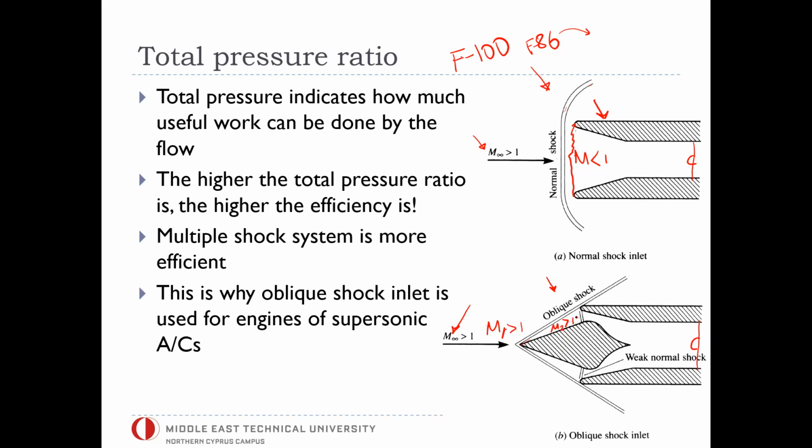So when the flow reaches right upstream of the normal shock wave, the Mach number will be barely above supersonic. So this normal shock wave will be very weak. You will have a very low pressure loss and then go to subsonic right after it. Then a very large area increase makes it go to even lower subsonic speeds. So the engine will be happy.